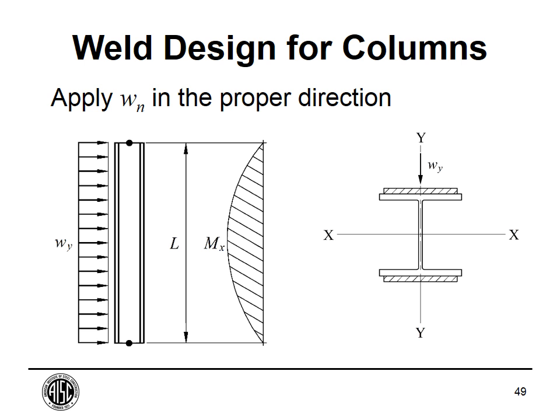But in our case, we want to get a moment at some point other than the location of maximum moment. So if we want to do that, we have to simulate what the buckled shape of the column is. And the buckled shape of a column is really similar to the deflection of a beam with a uniform load on it. So you get roughly the same shape. That's why I'm using a uniform load instead of a point load.